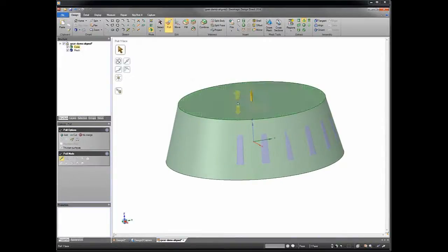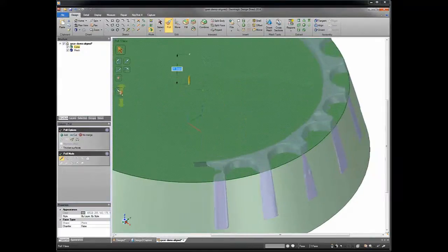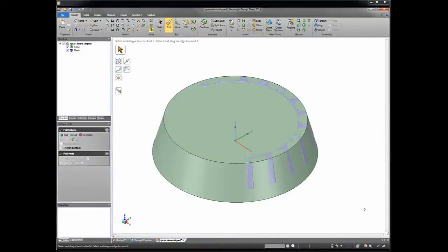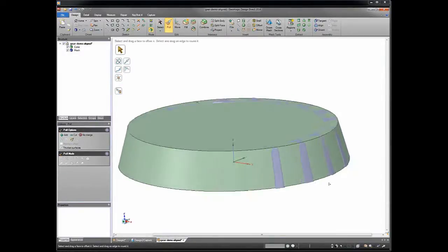Now what I can do is go ahead and use the pull tool, just like we've seen, and I can pull down, and then I can use the nice up to kind of get it centered. I may want to actually fit a plane to that top surface to get it more exact rather than just picking a single mesh point. That's up to you. You can certainly do that. And we'll pull it up just a little bit to create the right size.